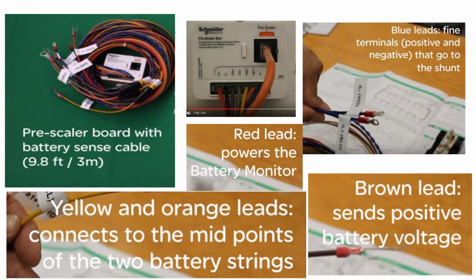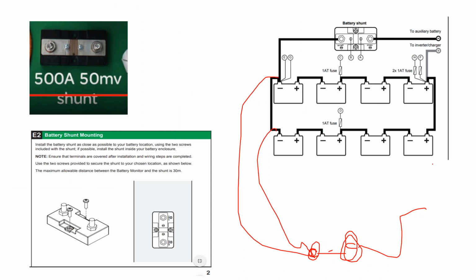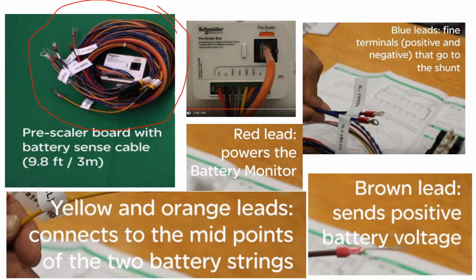Another inverter component that caused a little bit of confusion. This is the battery temperature monitor, and you're across multiple points across our battery bank. This E, G, H, F, A, B. So we're monitoring the shunt as well, and C. We're taking voltage readings across the shunt and voltage readings at different points in our battery system to monitor the battery.